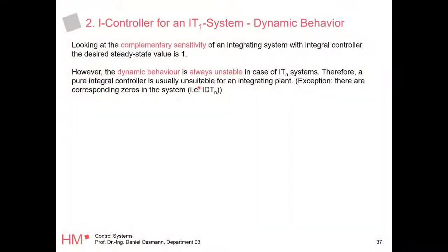We said we are only allowed to compute it if the final value actually exists. And if you have an unstable system, the final value theorem will tell you the final value is 1, but you need to check stability. If your system is unstable, it goes to infinity, but the final value theorem is not applicable then, because the final value does not exist, right? The final value only exists for stable systems. You can actually try that, but I show you the simulation to it.